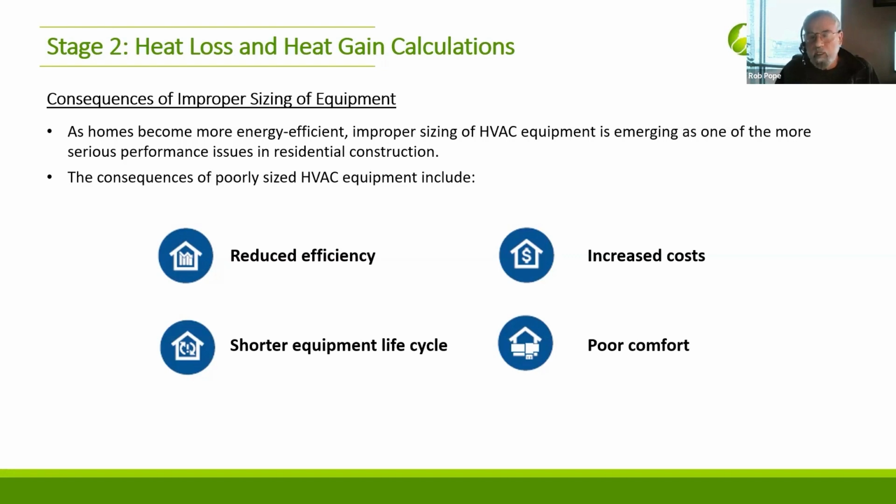If you get it wrong, not only does the system fail in many ways in terms of performance, you get reduced efficiency. If the system is oversized, it's going to short cycle. It's going to reduce the life cycle of the equipment and be uncomfortable. And you've also spent more money than you needed to, and there's no benefit to that whatsoever. There's no upside to